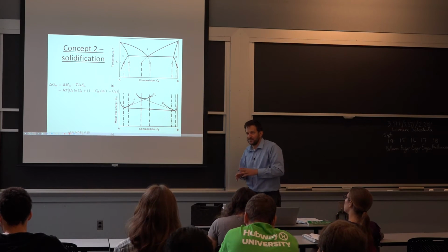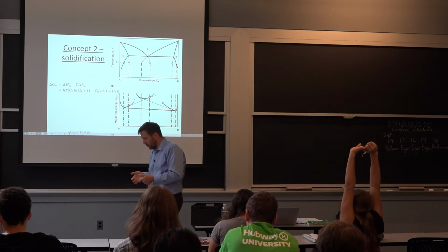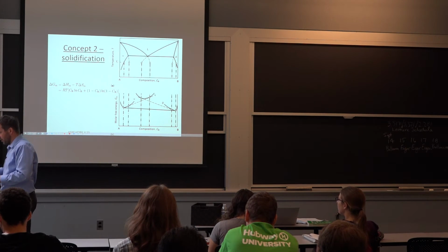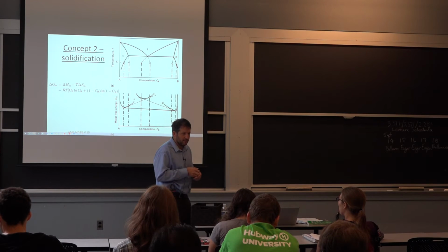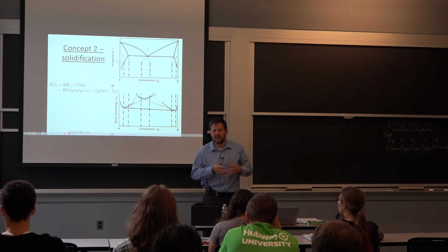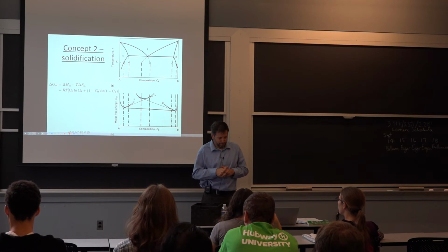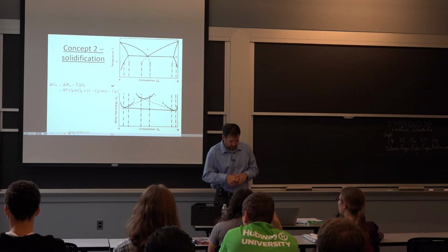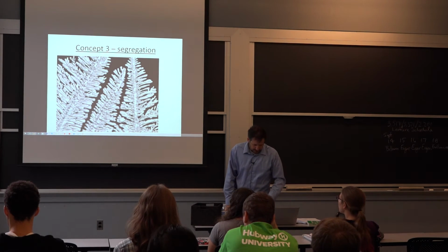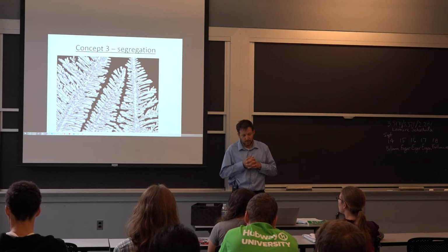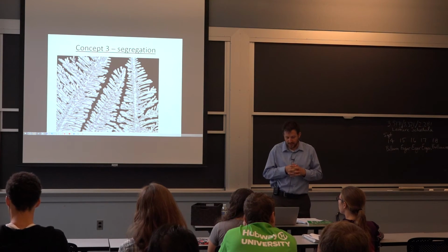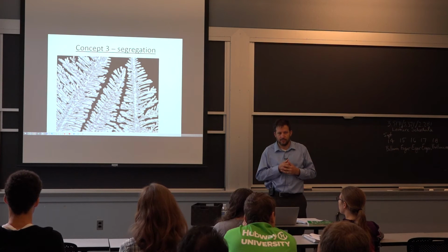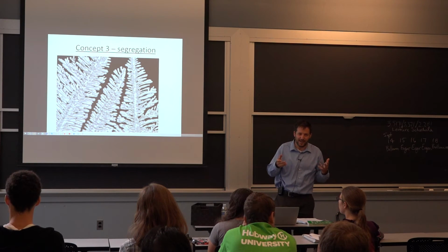So I talked about the advantages, right? I say, okay, so if I don't have a pure aluminum or a pure iron, I can cast at a lower temperature, and I'm going to have this mixed microstructure. So the main drawback to this, I'll show you this one first, is you will not form a homogeneous microstructure by default. What you will be solidifying at first is almost the pure alloy because the alloy has the choice.